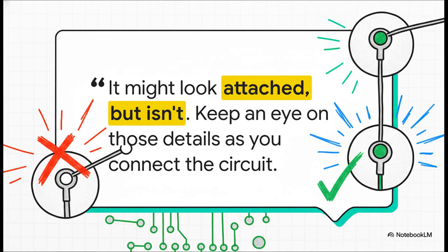Okay, listen up because this is a super important tip for anyone just starting out. When you're drawing wires with the W key, you have to make sure you see that little solid circle pop up when you connect to a pin. If you just draw the wire over the pin without clicking on that connection point, it'll look connected, but electrically, it's not. It's just floating there. This tiny mistake can cause massive headaches later, so always zoom in and make sure you've got that solid connection.